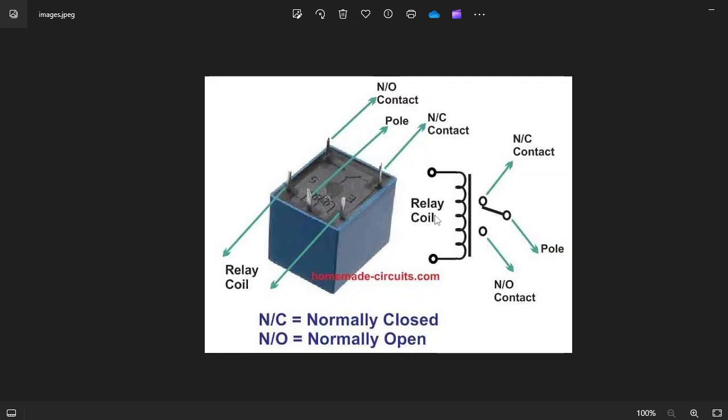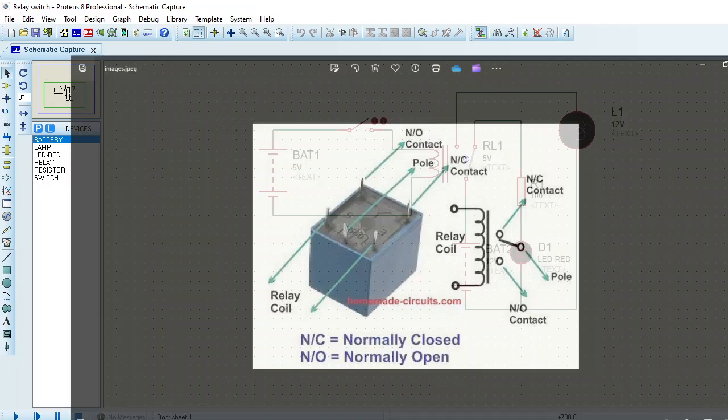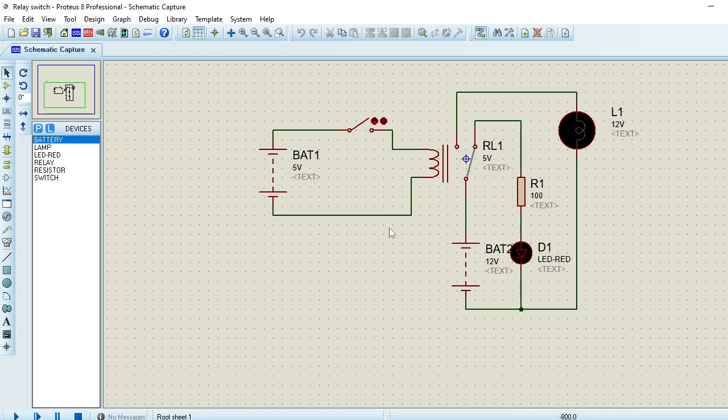Alright, so let's move on. I've explained how the relay works and told you what it is made up of. I can simply say that the basic construction of the relay is a coil, the armature, the spring, and the contacts. The key observation we made was that the input voltage of the source must also match the calibrated relay voltage. I've said that before.